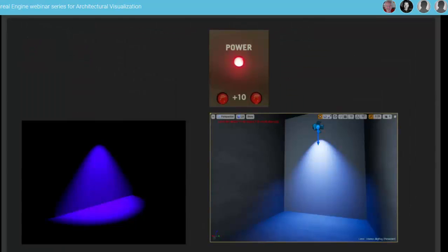But that's for tone mapping. What that means in practice for us, just this little test actually running with V-Ray, putting a spotlight of very, very high intensity. This is possibly, I think it was 1,500 or something like that. So here you see that as the spotlight gets massively intense, it's a blue colored spotlight shining on a white wall, but it gets massively blue, and that doesn't seem to really happen that much in reality.